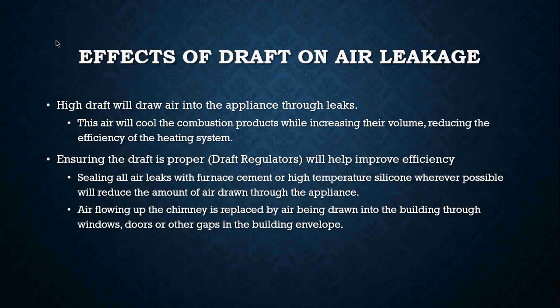Make sure that all the panels are on. Make sure all your gaskets are in place. Make sure your flue pipe is sealed and caulked and cemented the way it's supposed to be per manufacturer's specifications. Because remember, we only want to introduce the correct amount of air where we want the air to enter, and that's through the burner. We want the furnace to do the rest.